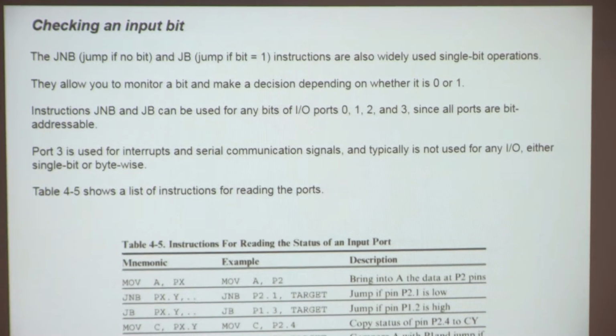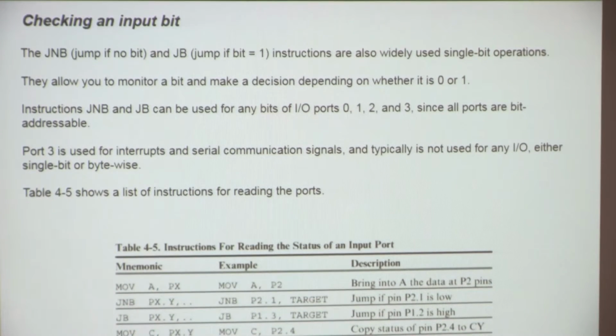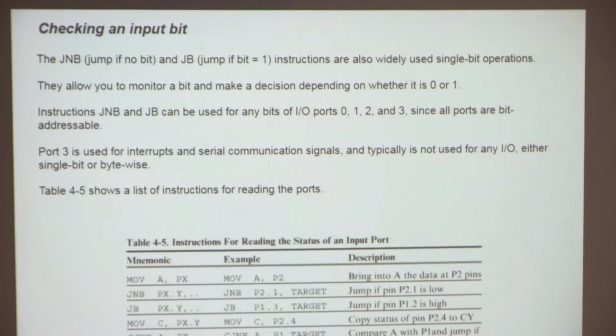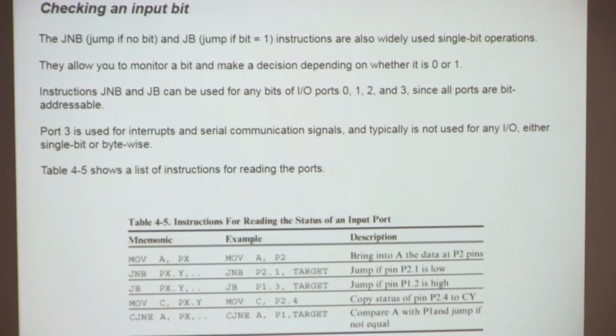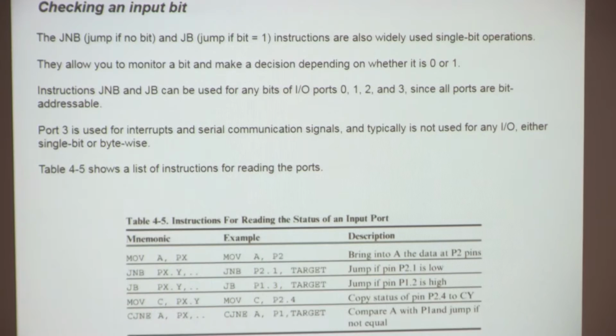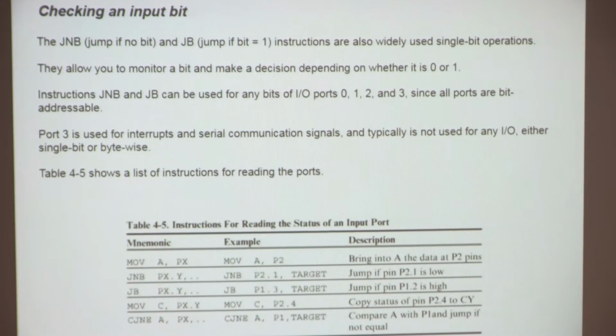Checking an input bit, because now remember with the 8051, with the port control, so with the I/O programming, we can send a bit, but we can also get a bit in, as mentioned, because you want to check something happened, and you do it for monitoring.